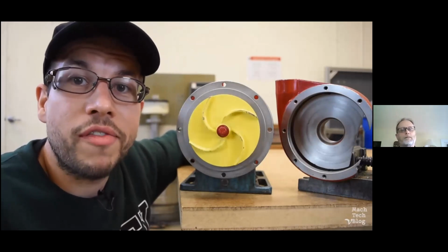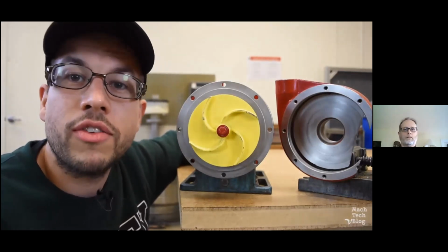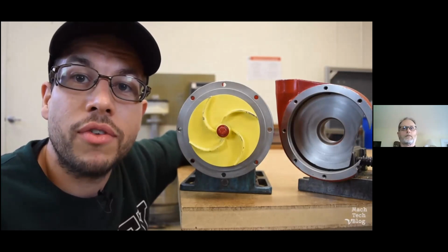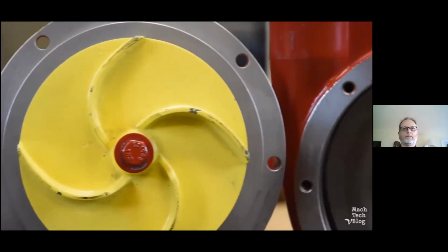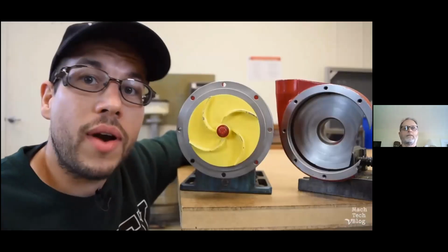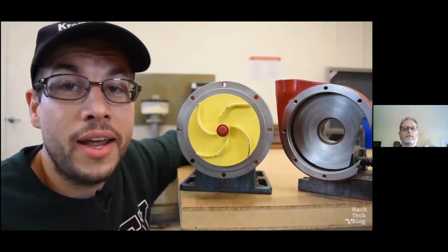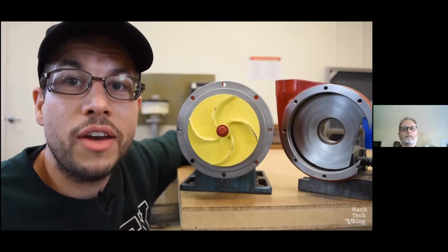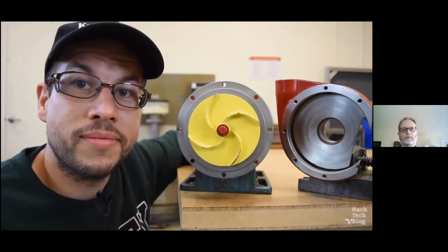Well, that's not really what the vanes are there for. The vane's purpose is to conduct the fluid along the smoothest possible path as it travels through the pump. Backwards curved vanes help to stabilize flow conditions at high speeds and reduce demands on the motor. The correct direction of rotation for this impeller is actually counterclockwise. And you can always tell the correct direction of rotation of an impeller just by looking at the way that the vanes are curved.